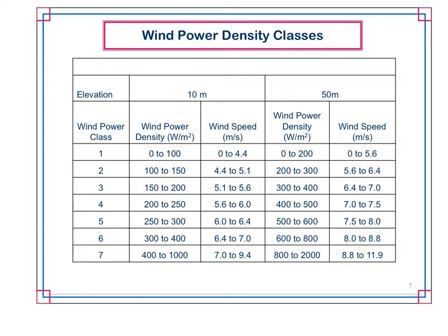So what we do, or what's been generalized, is depending on the elevation. So the wind at 10 meters versus 50 meters is going to look very different, right? Close to the surface, the Earth's surface is considered rough, right? Like sandpaper to the wind. So it's going to tend to want to slow down the wind. Whereas you get in higher elevation, it's not as rough, right? It's smoother. If you think about landmass, how tall are trees? 100 feet tall. Mountains, hills, whatever. Those can have some effects on it. Buildings, right? 50 meters is approximately 180 feet or so, 170 something feet. So that's not a particularly tall structure, so that is going to tend to slow the wind down.